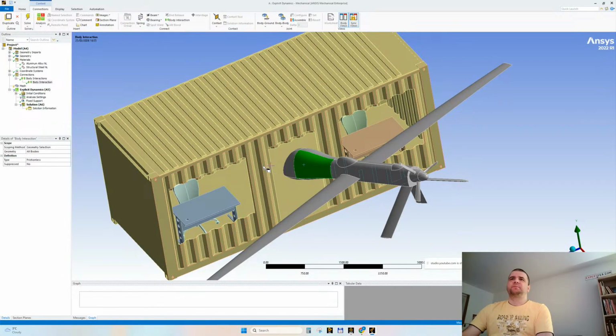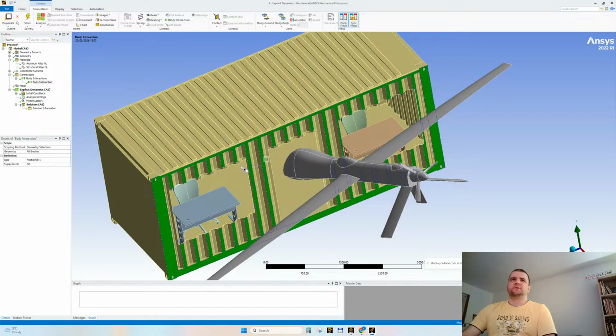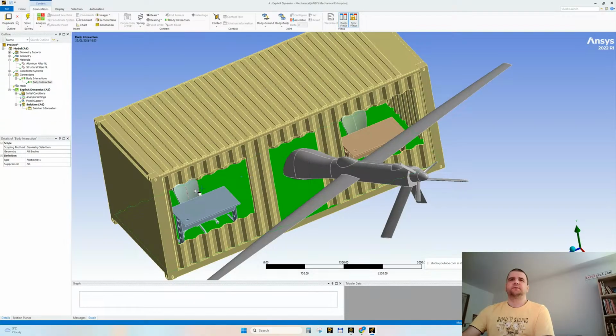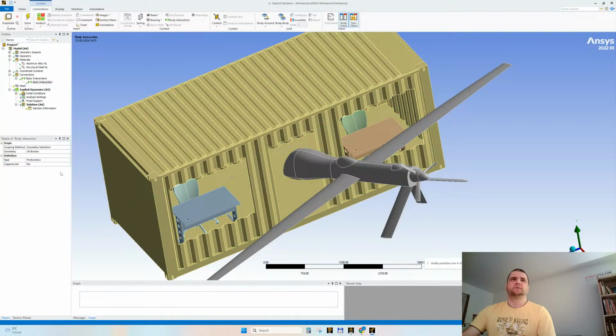The friction coefficient between aluminum and steel is usually 0.5 or higher. So I was wondering, this and this 0.5. Yeah. Let's assign, as I said, 0.5, and I think a similar coefficient can be applied here on the dynamic, but let's leave it like this.